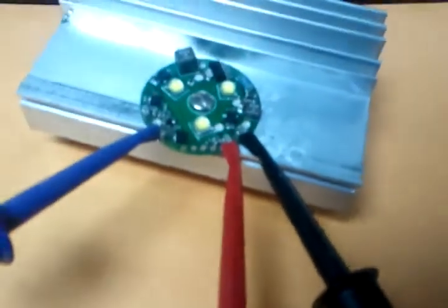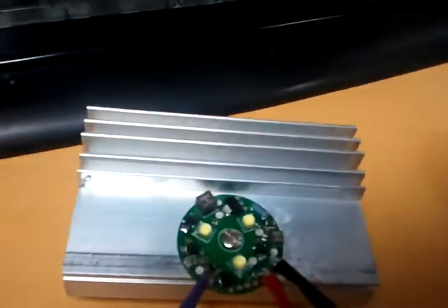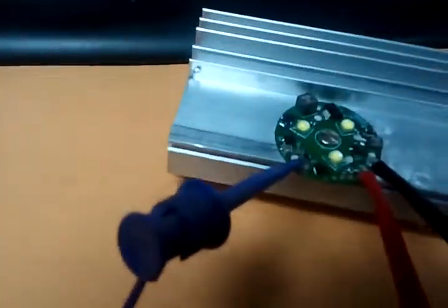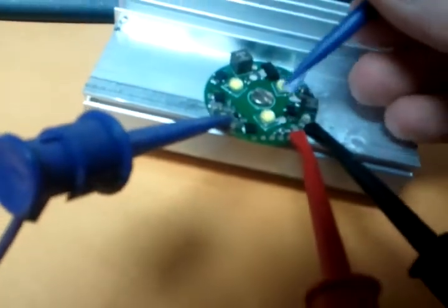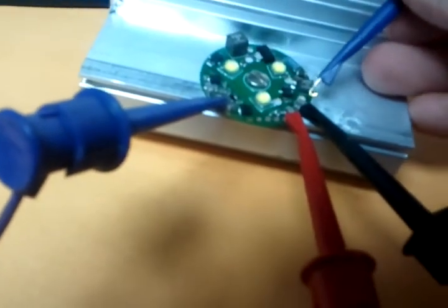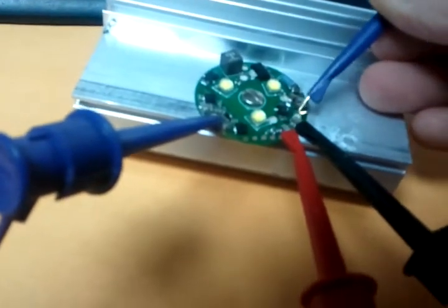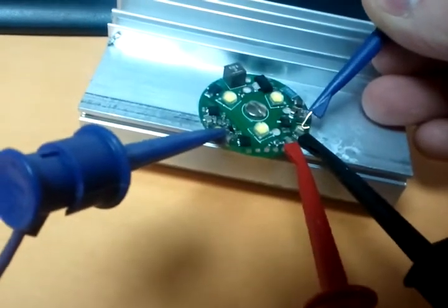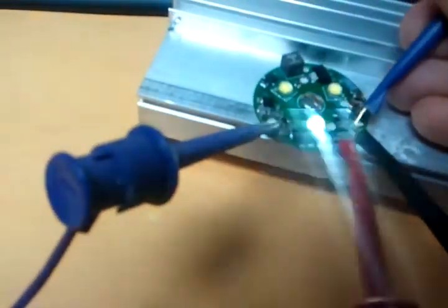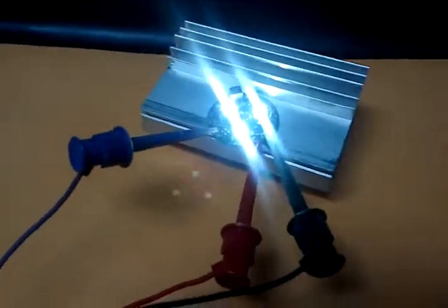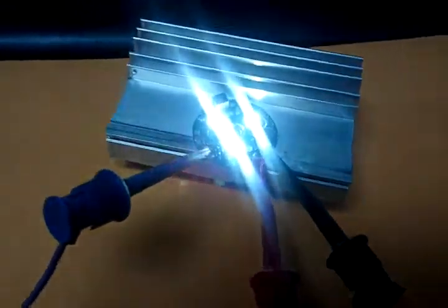So this is the mode input, and in order to switch modes, what we have to do is take the mode input and pull it down to ground. This is how you'd hook up your switch between the mode input and ground. And you can see when something didn't work. Oh, it helps if you turn on the power supply. Okay, power supply is on. So now when I touch ground, there we go. That's the first mode we programmed, which is a very low setting, and it worked perfectly.